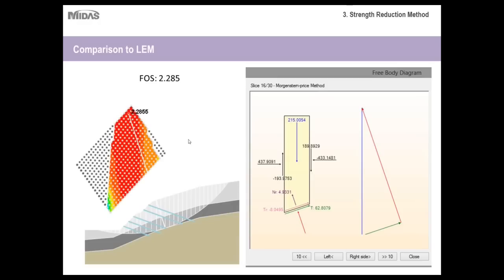Okay, and once again, as you can see, the grid range here in the post-processor and the results mode, this area here is red, which represents the critical area. So here's where your factors of safety would be the lowest. And once again, it'll isolate the arc failure surface that corresponds to a point on the grid, and your minimum factor of safety will be isolated. So in this case, the factor of safety is about a 2.855.